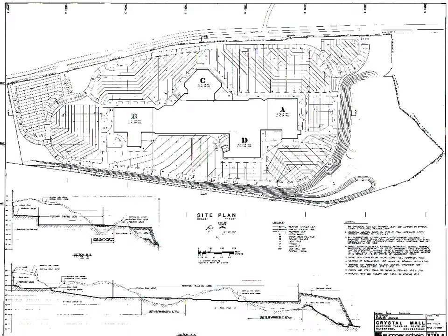And what you're really trying to do in a building like this is provide large flat areas for buildings and for parking. The maximum slope that is allowed, or that people will walk up in a parking lot, is a 3% slope. That is, the ground goes up 3 feet in 100 feet, which we think of as being quite shallow. But if you're driving on an interstate, you'll sometimes come to these signs that say, caution, steep slope ahead, and those are like 5 or 6% slopes.